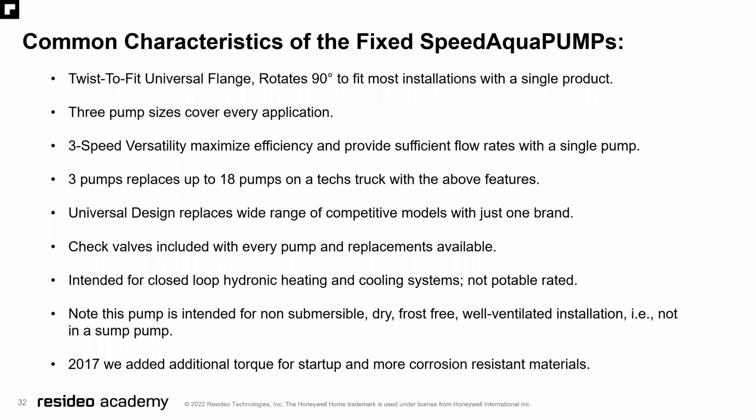They're intended for closed loop hydronic heating and cooling systems. We do not have potable rated pumps. And again, this pump is intended for non-submersible, dry, frost-free, well-ventilated installations. Cannot be used as a sump pump.